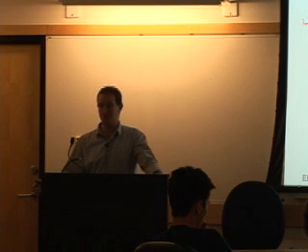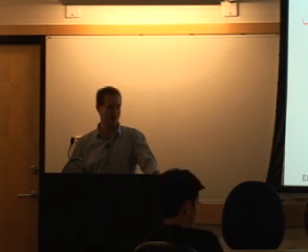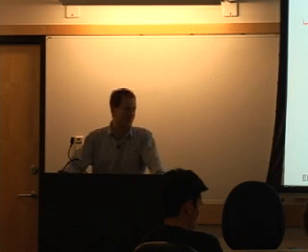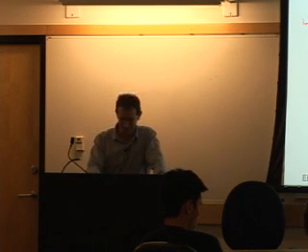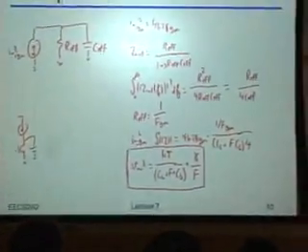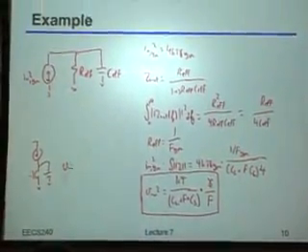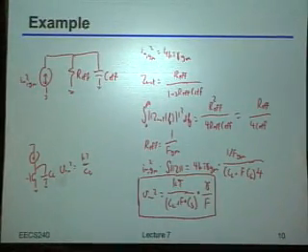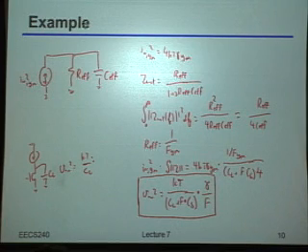By the way, what is the total integrated noise for a common source amplifier, open loop, driving some capacitive load? We said that before: if we had an open loop amplifier like this just driving a capacitor, you would get that the output noise is kT over C, and let's be explicit, let's call that CL. Is that it? Is there something else in there?